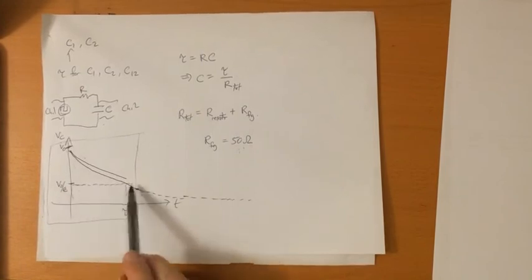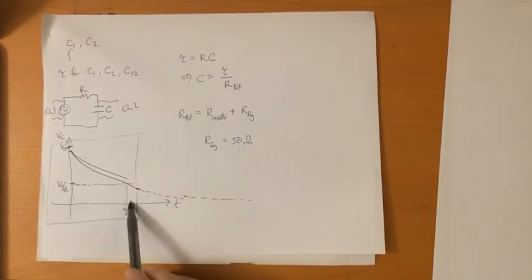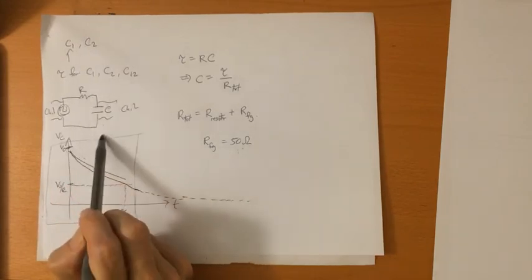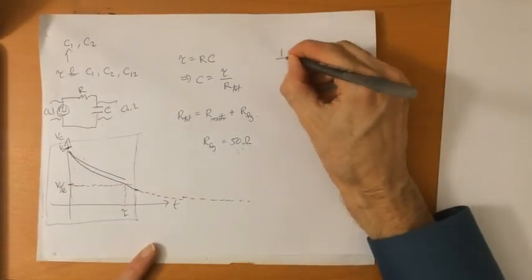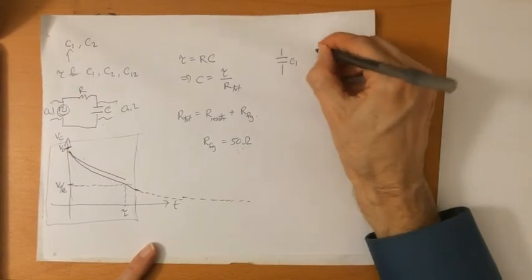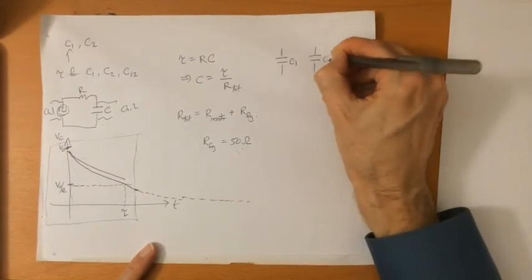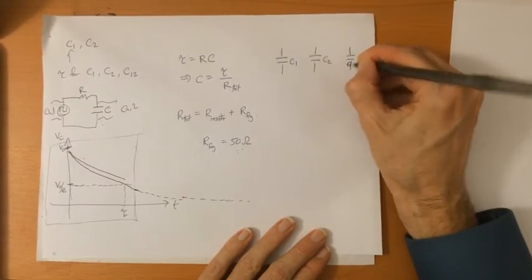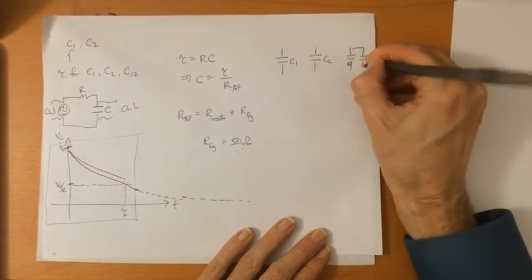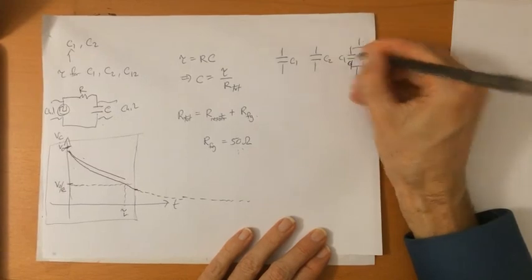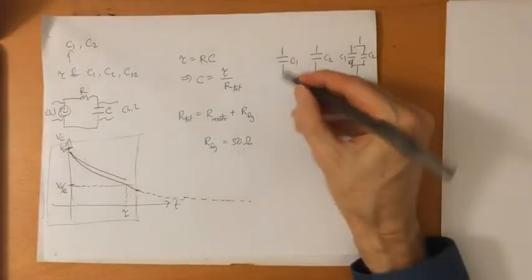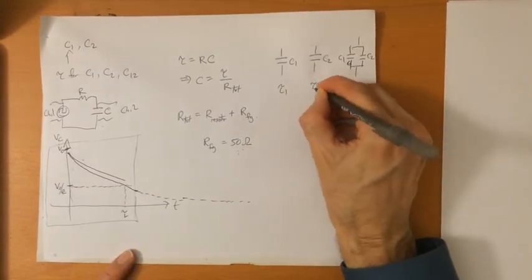And then what I'll do is I'll actually give you the cursor's measurements for C1, C2, and then the parallel combination of C1 and C2. So you're actually going to be dealing with these three capacitor sequences. This is going to be a parallel combination here, C1 and C2. So you're going to be working with these three, and you're going to get three time constants.